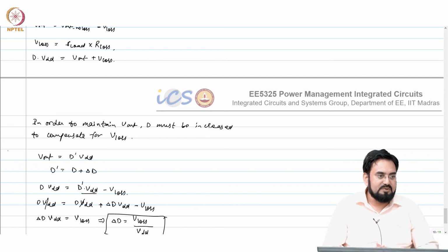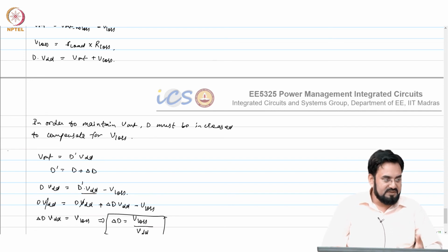So, it will have complex poles. So, now you have a double pole and a complex pole. If it is a very high Q, then at resonance you will get a 180 degree phase shift right away. So, inherently it is an unstable system if you simply connect the negative feedback. So, you need to stabilize it, and we used to compensate it.